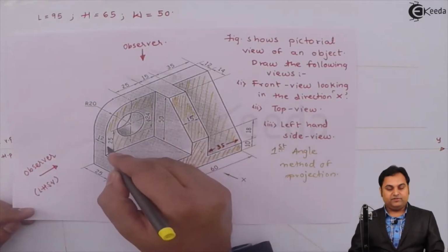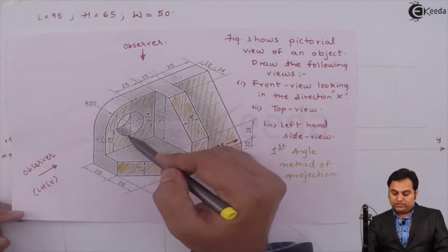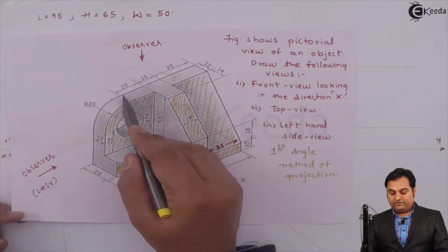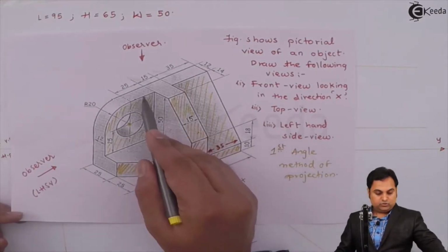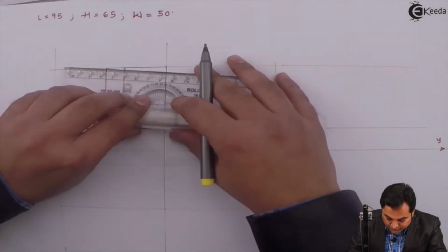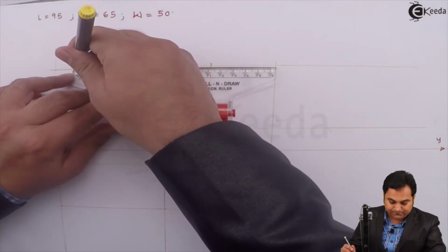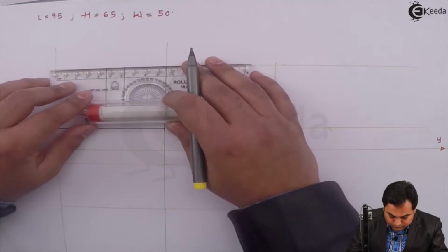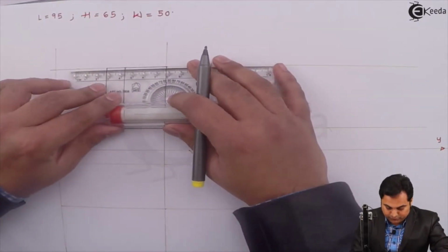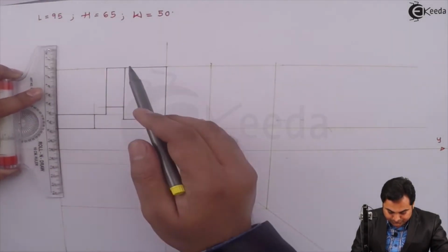So I'll draw this surface. Here the center of this semicircle and circle both are same, located at 25 length, where this 15 plate is ending. So after that 15 plate, I am measuring 25 with the help of a light line, and then projecting it light downwards.